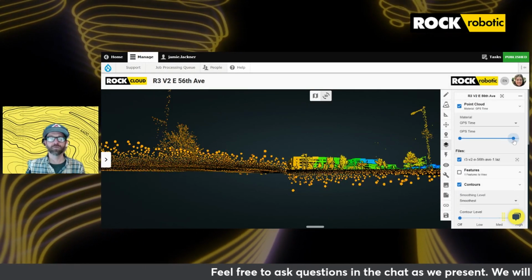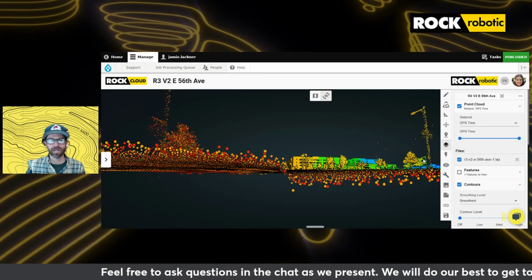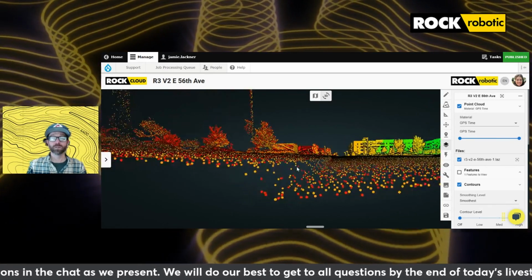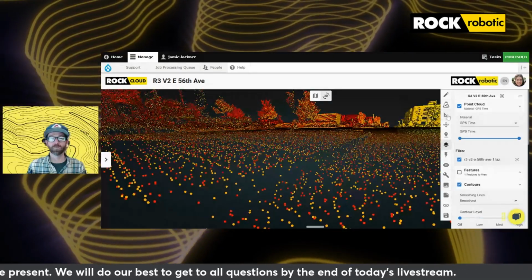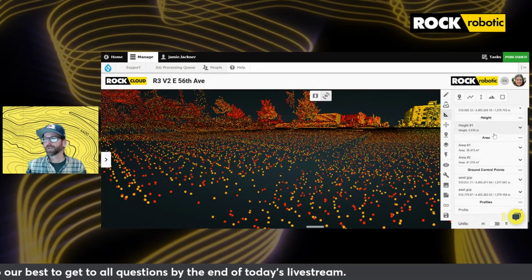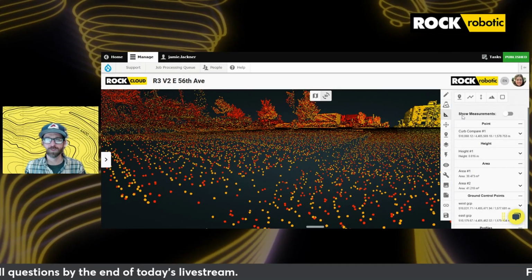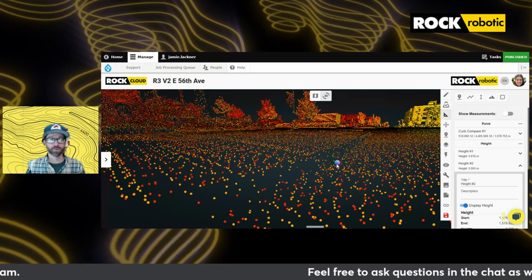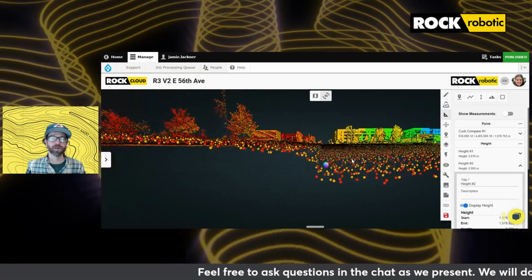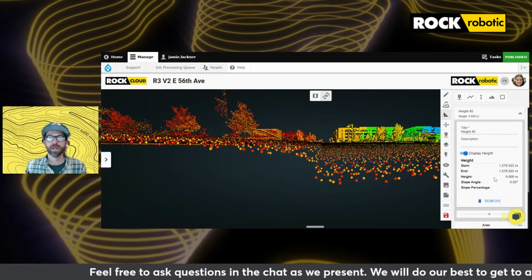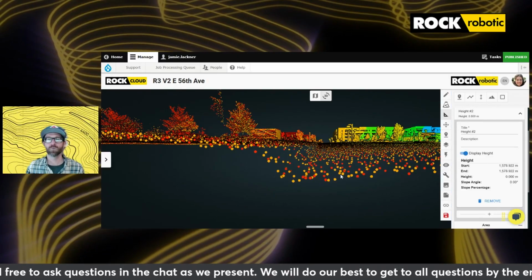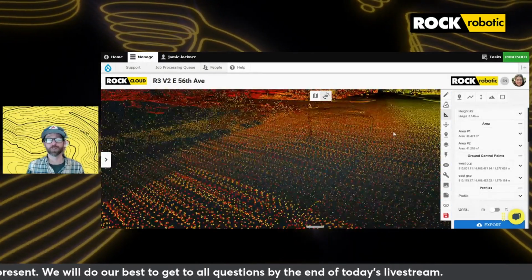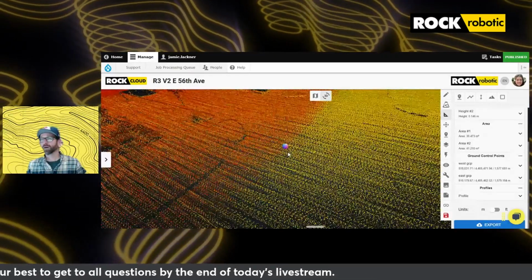So what we have there, we can do the orange to the red, see that red come in, and we're looking at great overlap. And we can also make our measurements. We didn't do the height measurement in this one specifically for the curb. I've just spent enough time out at this site to tell you they are vertical curbs. We're getting a vertical measurement on them. You can see that visually. What we can also do is look at the flat surfaces of the road and use our GPS time slider to again verify that accuracy.